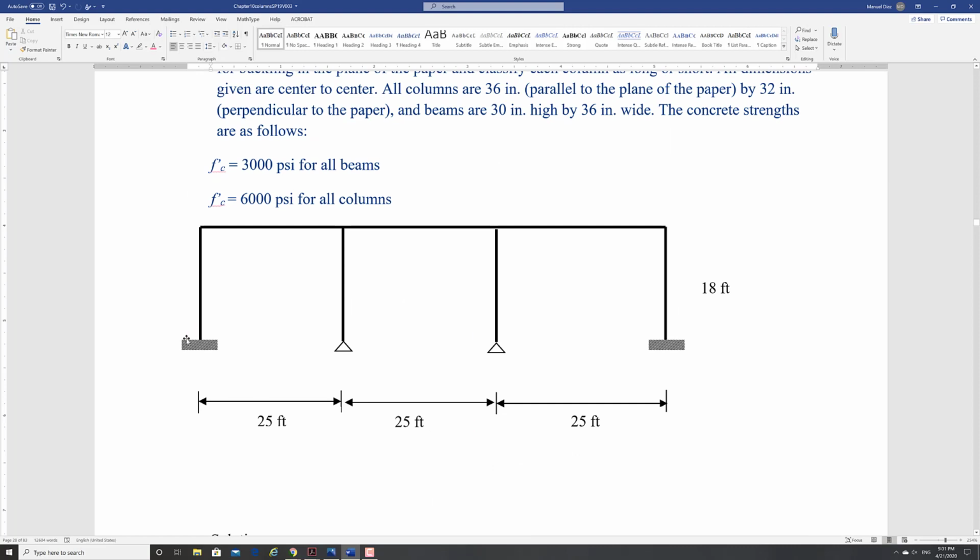So if we're going to do this exterior column, right, one psi value is going to depend on this condition that is fixed, right? And I already gave you the value for a fixed, 1. But the other one here is the other psi value I need to find. Notice that at this joint, you have one column coming to the joint and one beam coming to the joint. So your psi value will have then the EI/L of one beam and the one column.